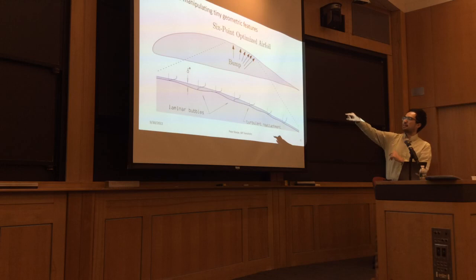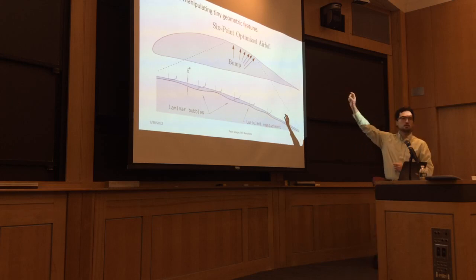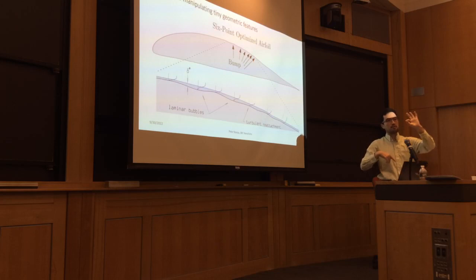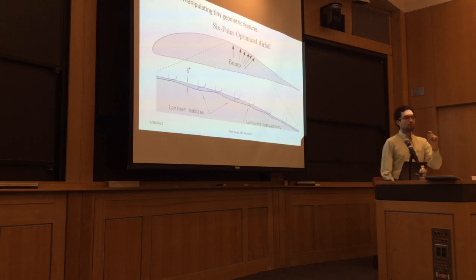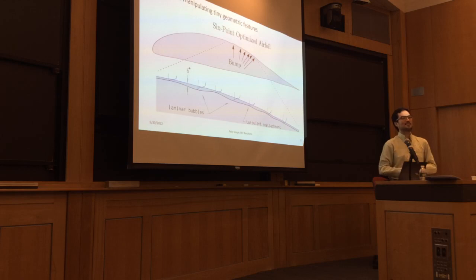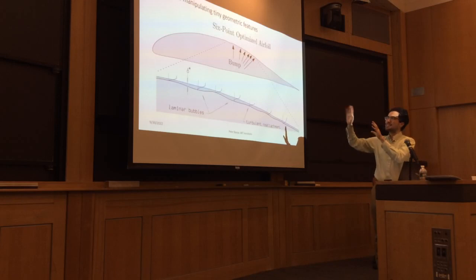And the reason is basically that as the airflow goes over the top of this airfoil, it's starting out laminar and nice and smooth at the beginning. At some point, it's going to trip to turbulent and become a chaotic mixing flow. And the way it's going to do that is by forming a little laminar separation bubble. That's a little bubble of air on the top of the airfoil. And what the optimizer is doing is cutting a hole in the airfoil to exactly fit that bubble, right at the lift coefficients that we asked it to do. And that way, the outer airflow isn't actually seeing that bubble, which would normally cost us a drag penalty. So we've got 6 points here, one for each of our lift coefficients. But in reality, this isn't something that we can actually make.